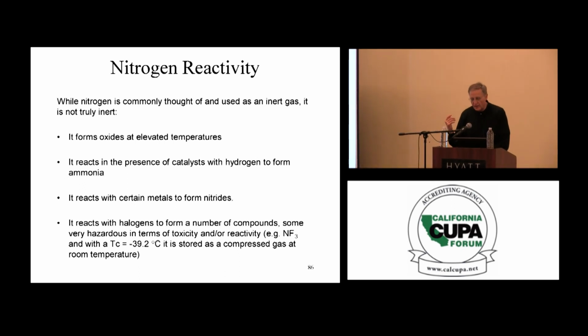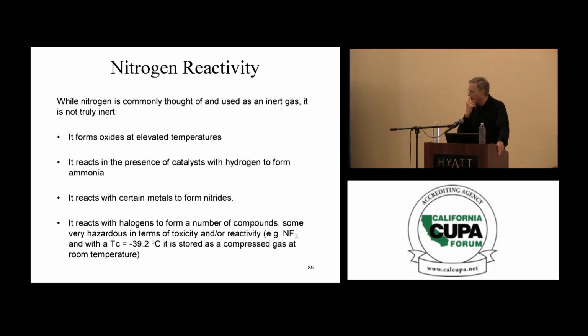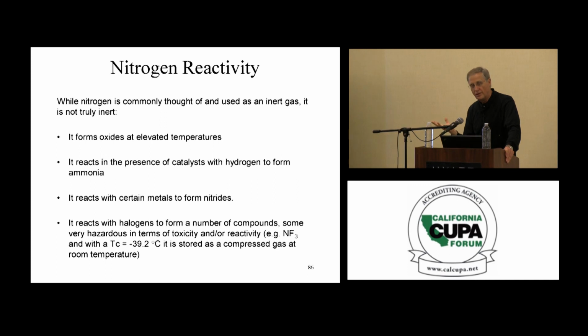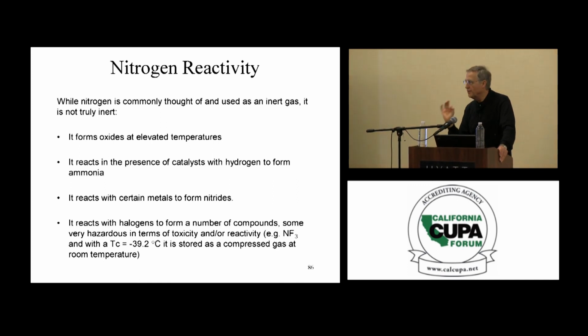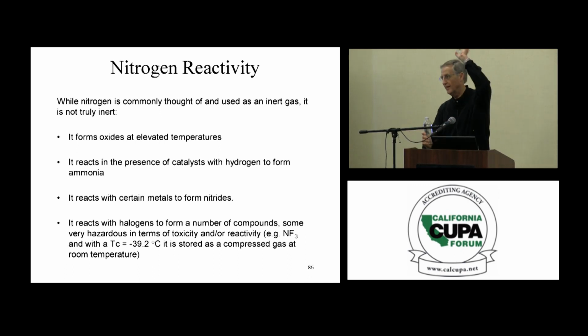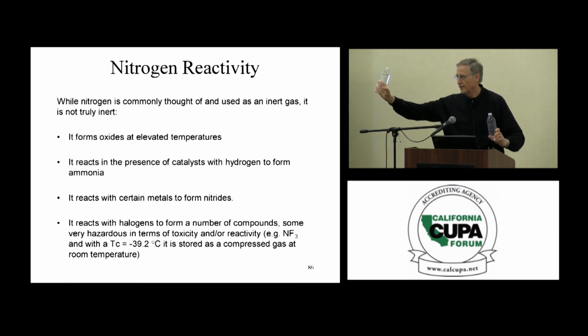Now, when you get the slides, you'll see information on nitrogen, and I talked about this issue of whether nitrogen is a liquefied gas or a compressed gas. So with nitrogen, because of its low critical temperature, at room temperature, nitrogen will look like this inside the vessel, not like this.